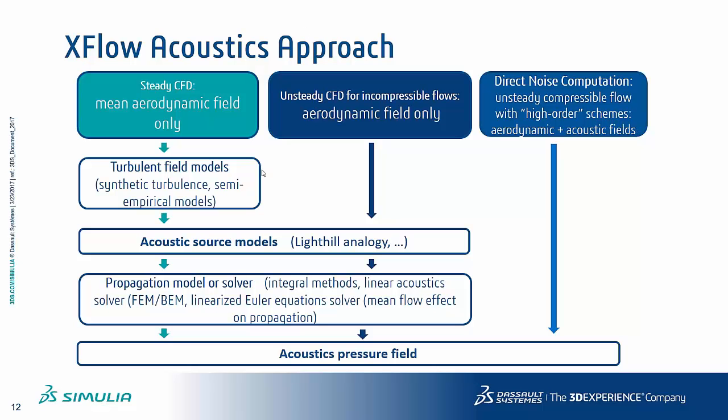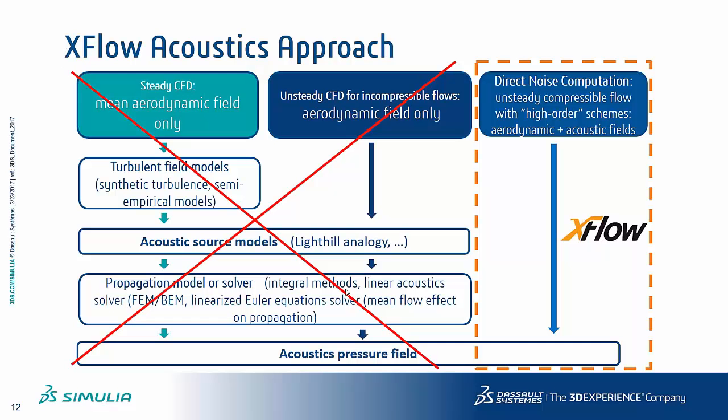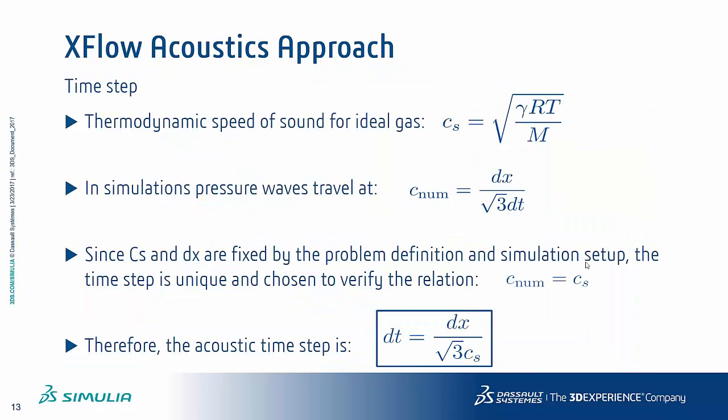All right? So this is where we stand with XFlow, and we actually get rid of all those models here: turbulence, acoustic source, and propagation. And we just get our acoustic field directly through the pressure fields. So we just have to measure waves propagating and we'll get acoustics.